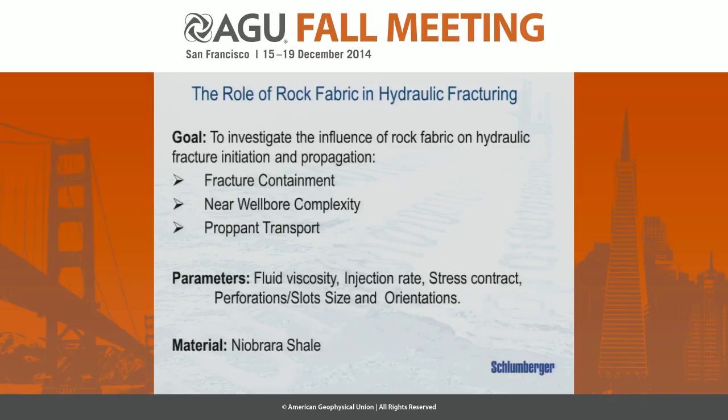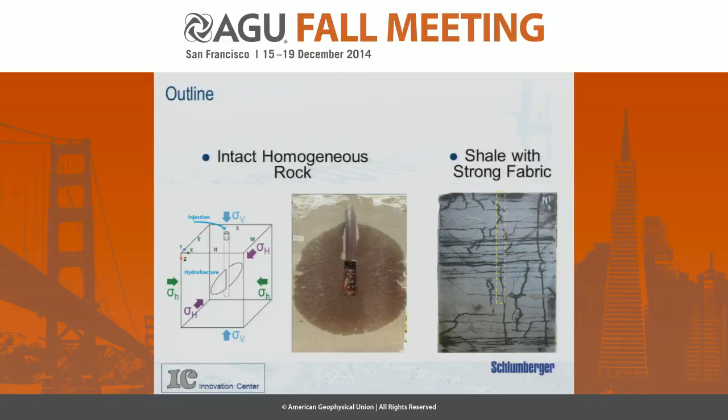Today I only have a chance to show you results of the influence of rock fabric on fracture containment, on near wellbore complexity, and also on the aperture of the hydrofracture opening, significantly influencing proppant transport. At the beginning of my talk, as a reference, I'm going to demonstrate results obtained during hydraulic fracturing of intact homogeneous sandstone samples.